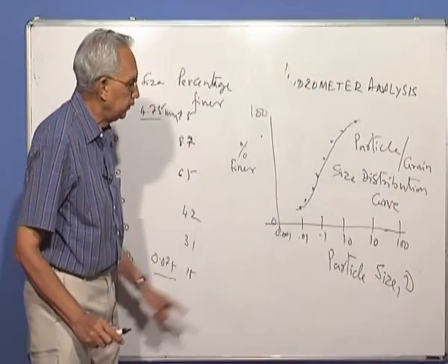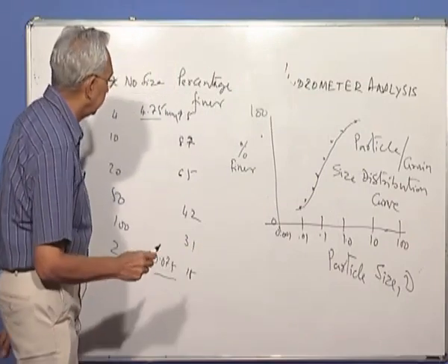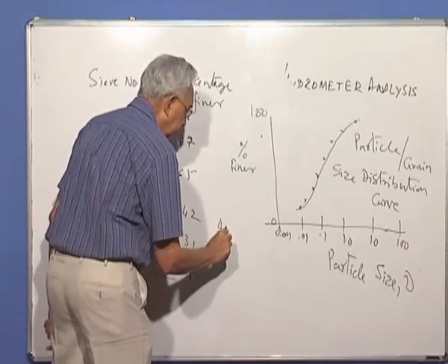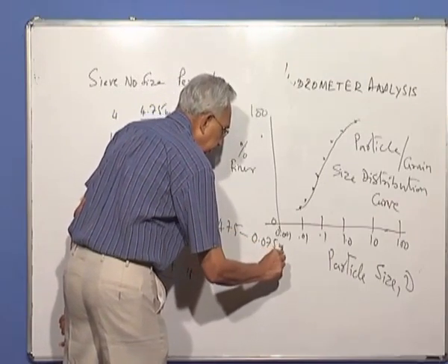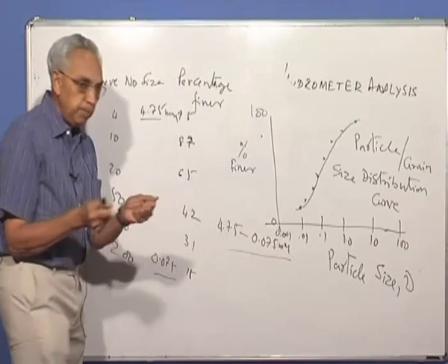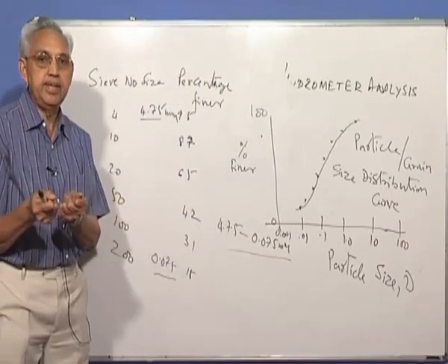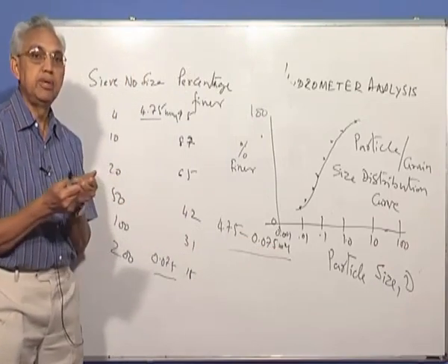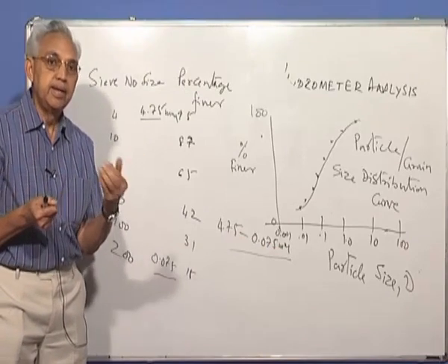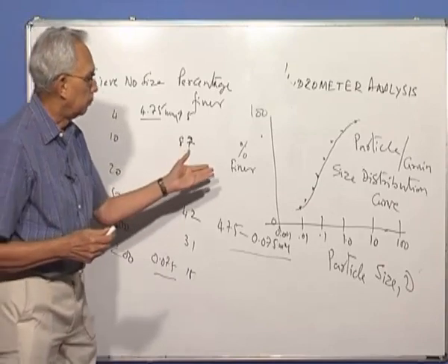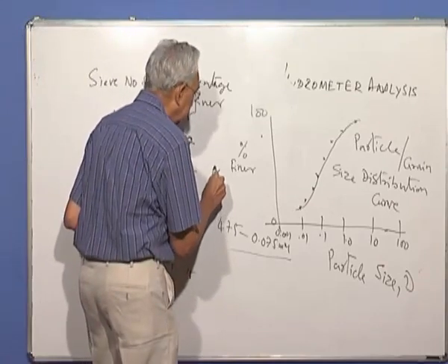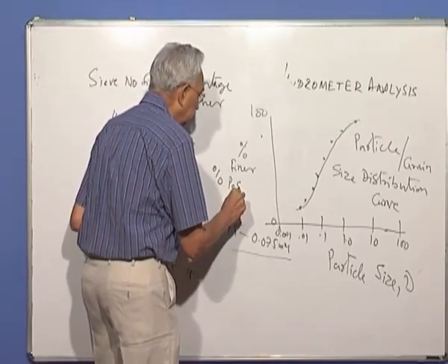What you can do from sieve analysis is, from 4.75 to 0.075 millimeter range, I can simply put it on a sieve, shake the soil, collect the amount of material retained, and then I can find out how much is passing through: percentage finer or percentage passing through.